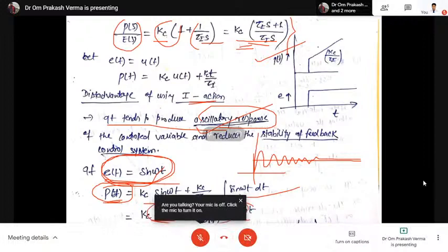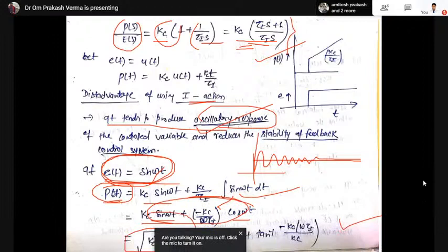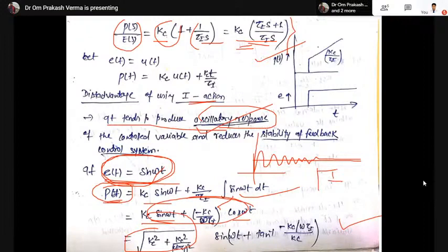Just solve this equation and we get the amplitude, as we have discussed in one problem, 1 upon s plus 1. I told you earlier, this is a question asked in the GATE examination also. When you supply sine omega t, you are asked what the response of the system is. I told you at that time, when you supply a sine omega t or sinusoidal signal, your output must be sinusoidal, with only a change in magnitude and phase. So here also the input is sine omega t.